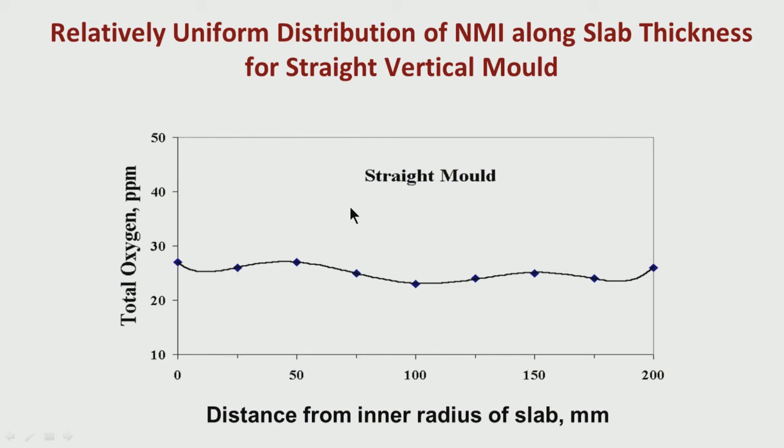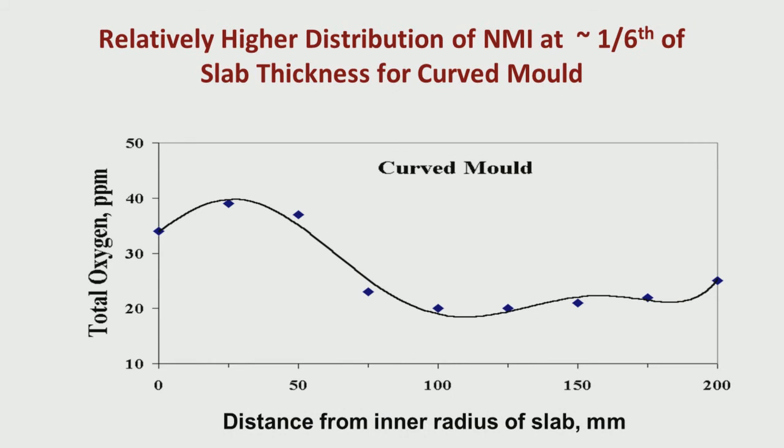If you have a good inspection facility, then you can find out at what stage these defects are coming out and what is the distribution of the defects, like whether defects are coming more on one surface or near both the surfaces. If you roll this slab, we will find that defects are coming more on the surface which corresponds to the inner radius of the caster.